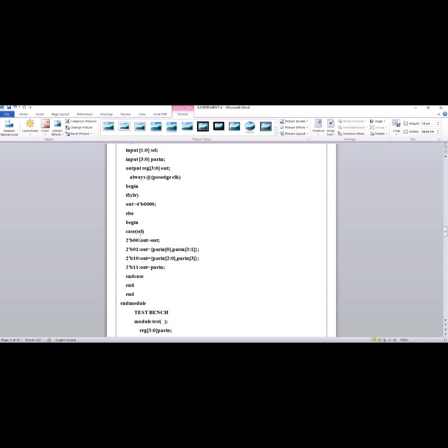So if I want a left shift, the selection pin you have to choose as 1, 0. Since it is selection 0 and 1, I have selected a 2-bit binary value. Out is equal to the right hand side 3 bits coming to the left side, and the last bit goes to the right hand side. That is the dead end of your right hand side.